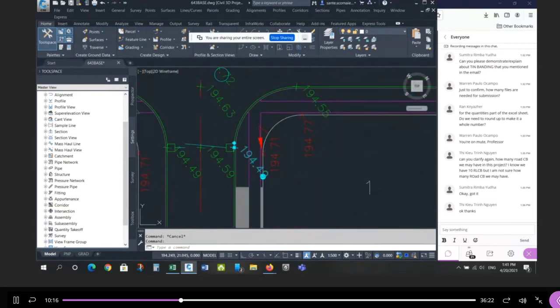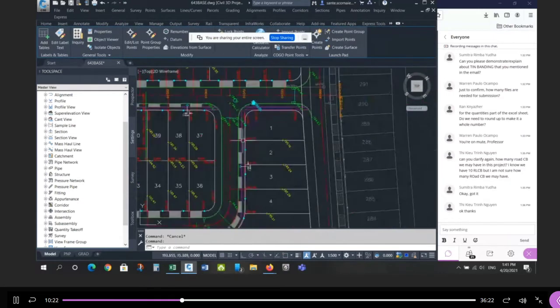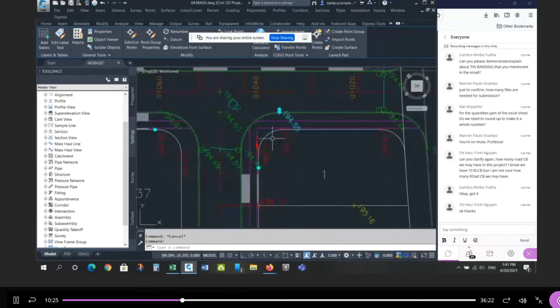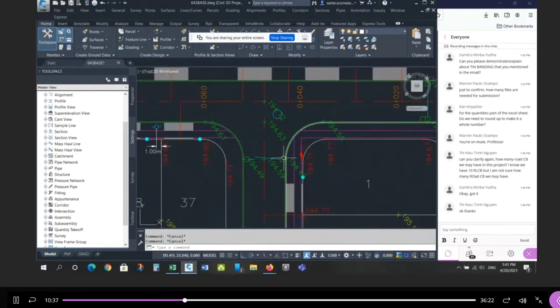This one you'll see 49 and 55. It's only getting water from here across to here. That's it. This little short distance, and then a whole bunch coming from this side. So if you wanted to make an argument for whether you need a double catch basin, I would maybe make this one a double catch basin, but not this one. Okay, so it depends on how the water is flowing, right? There's just a little bit coming this way.